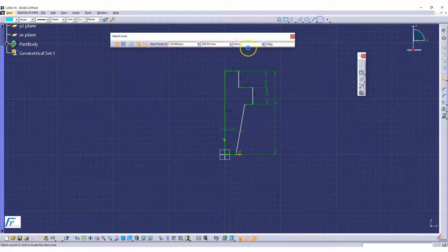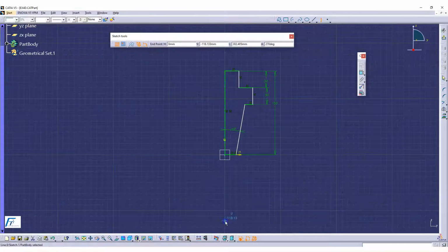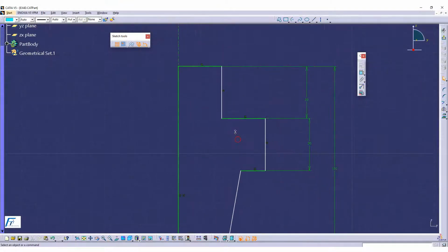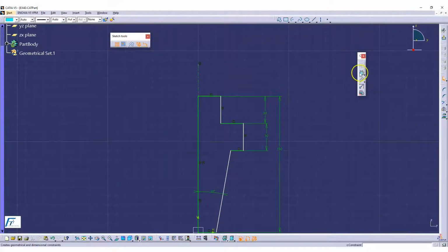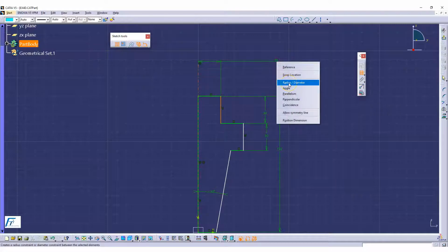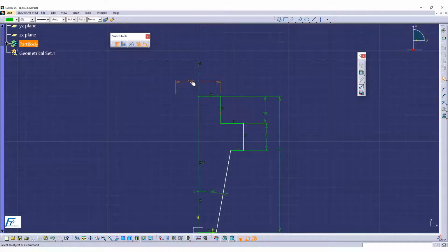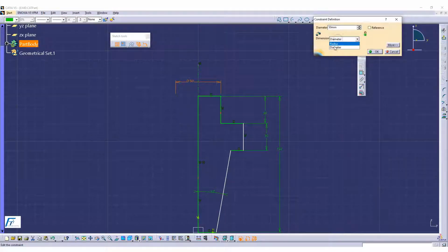And I'm going to draw an axis system. See this? And that axis system has to be constrained. Put it in normal view and make this constraint. That axis is constrained. Now what I would like to represent is that this is a cylindrical component which I'm going to shaft, as you saw. Select this one and select this axis. Select this one and this axis. Select this one and this one. Right click and you can see this radius. In this case, this is my radius, right? Just double click on it and represent this radius.